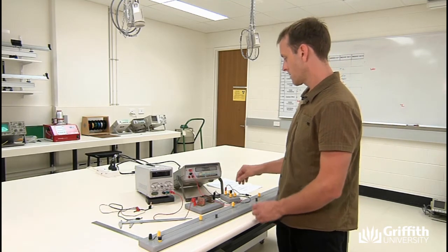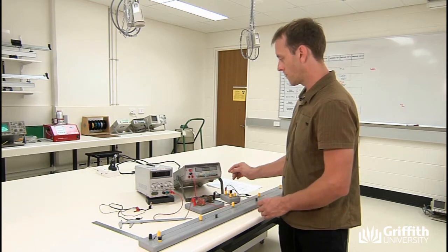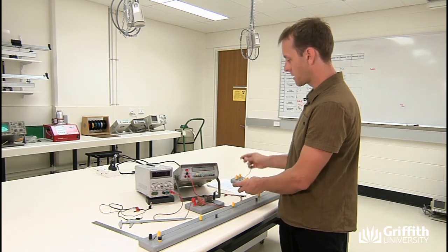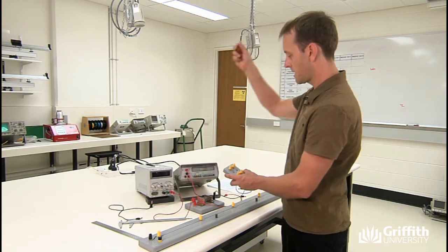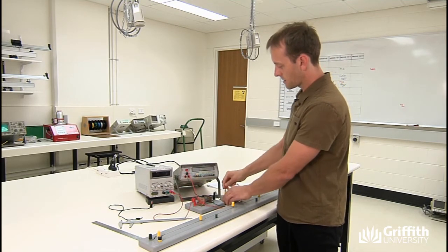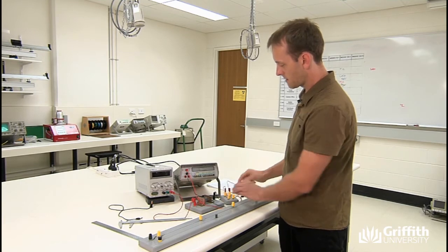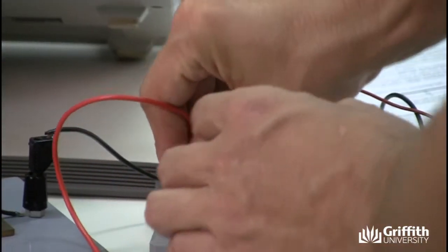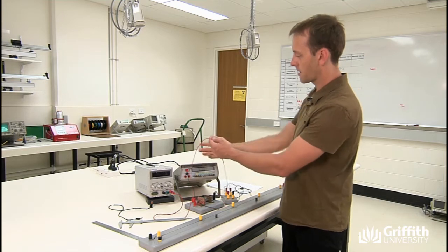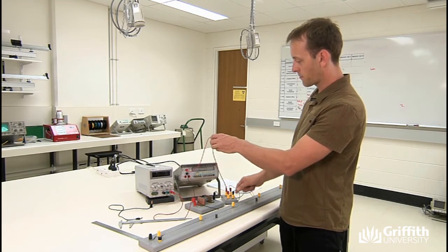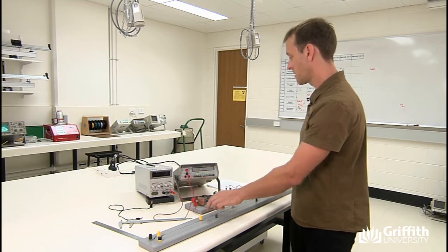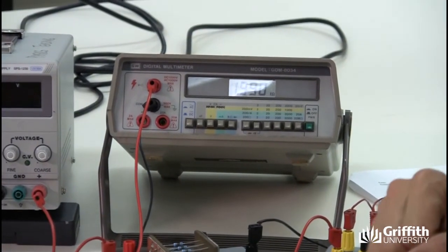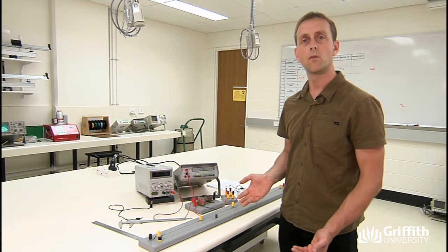So let's try then, turn your multimeter off. Let's take your resistors and wire them in series. Take some of these wires here, and if you connect this end to this end, these are now connected in series. We can measure the resistance like this, coming from your multimeter through one resistor, back through another one, and back to your multimeter, so that's in series. Let's switch it on again, and you can see that it measures about 2 kilo ohms, very close to 2 kilo ohms, which is what you'd expect for resistors in series.